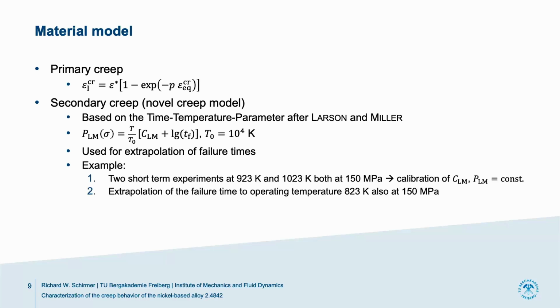To give you an example, you do two short-term experiments at higher temperatures, but at a specific load. You calibrate your parameter C_LM, and then you can plug in your operating temperature and calculate your failure time.